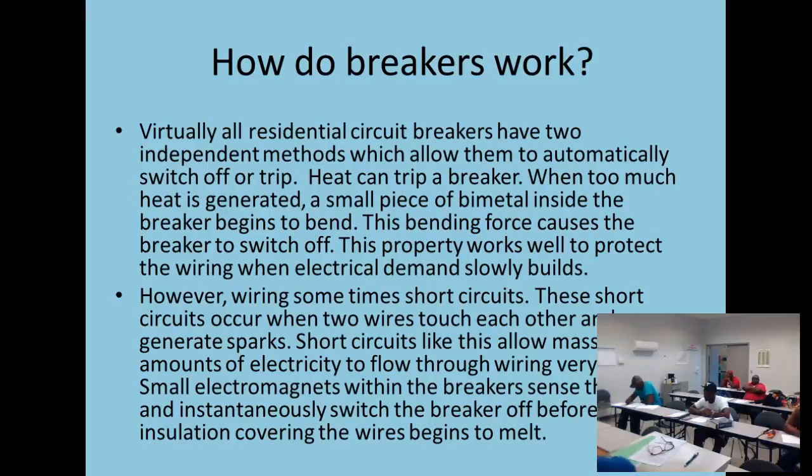You sometimes see that when you take certification tests. What are breakers for? They're to protect the wires. They're not to protect us. They're to protect the wires, right? So this breaker has two methods of safety. One is from bimetal, right? When I have two pieces of different, dissimilar metals fused together, and we apply heat or remove heat, there's a warpage. Metals contract and expand. And so we use a bimetal that cuts the power, and an electromagnet.